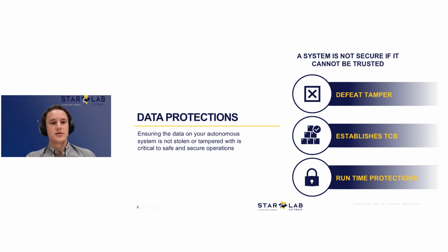But from the very beginning, each stage of code that runs validates and verifies the next one. And maybe you have something like a TPM on your device that is measuring the boot process to let you know if anything is happening that shouldn't be. As you go through boot, you want to make sure that nothing has been tampered with, so that when your system is running, you know that you can trust it. So we go through the bootloader, we go through the kernel, and all the way up through to your system itself, the rootfs, and ensure the integrity of all of those components.